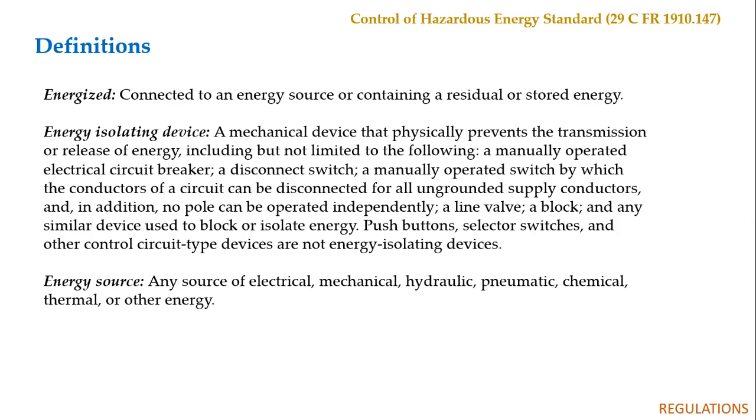The next definition is the energy isolating device. A mechanical device that physically prevents the transmission or release of energy, including but not limited to the following: a manually operated electrical circuit breaker, a disconnect switch, or a manually operated switch by which the conductors of a circuit can be disconnected from all ungrounded supply conductors, and in addition no pole can be operated independently, a line valve, a block, and a similar device used to block or isolate the energy.